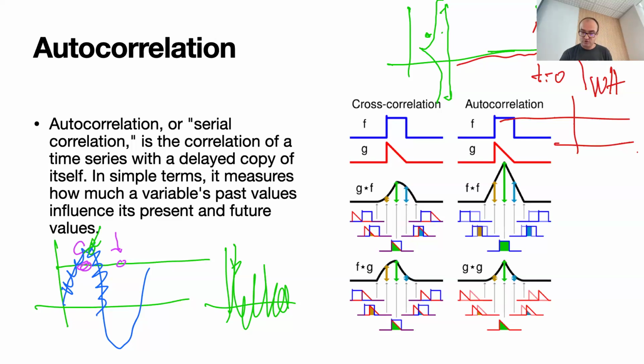For this to work I would need a Dirac signal, which I cannot generate. But because I'm not working in the time domain, but doing statistical wizardry, a formal mathematical concept, I can take white noise and generate a signal that has a flat spectrum. This is the main trick, the autocorrelation stuff.